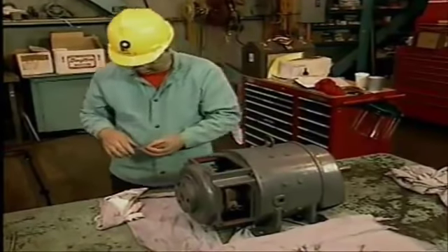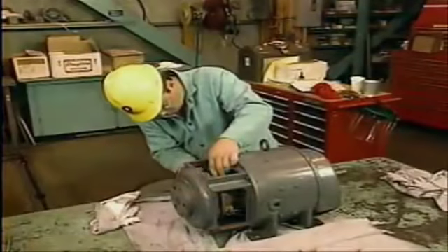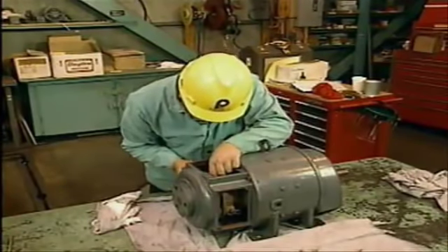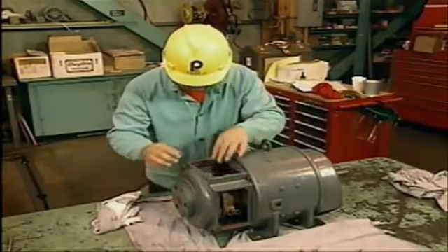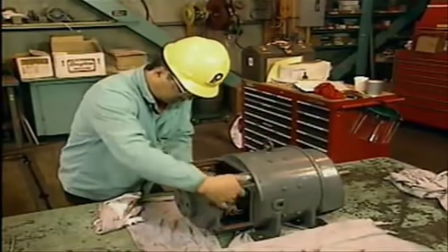All traces of carbon dust must then be removed from the motor. The next step is to install the brushes. After they're placed in the brush holders, the brushes are moved up and down to make sure that they can move easily. The next step, if necessary, is to set the amount of tension applied by the brush tensioning devices. The tensioning devices in this example are set by the factory and are not adjusted.